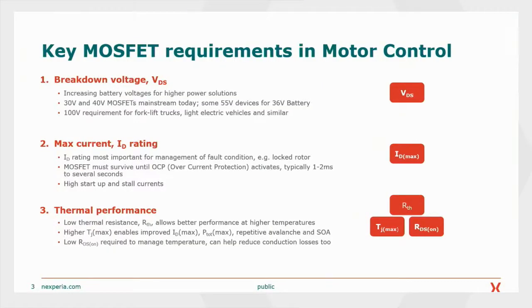Now, selecting a MOSFET appropriate for motor control, the items that need to be looked at are the stalled current capability, as well as startup, where the high current is needed. I'm not stating the obvious here, where the nominal current is normally what people look at in a MOSFET, and that nominal current tends to be 50% of the device capability. What we need to cater for, and we do, are the situations which are now part and parcel of the normal expected operation of the motor: the locked motor, as I said, and the high current startups.